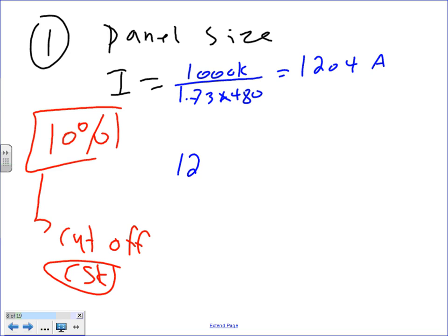The rule is 1204. Please go to table 3-13 this time, because 13 will give you the switchboards, since we ran out of the panel boards. We're going to go to switchboards now. What's the next standard? Look at the three-phase, not the single phase, the three-phase.